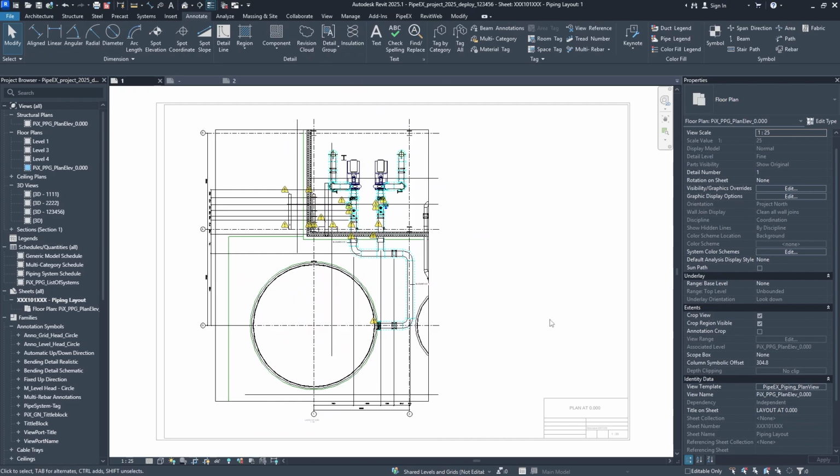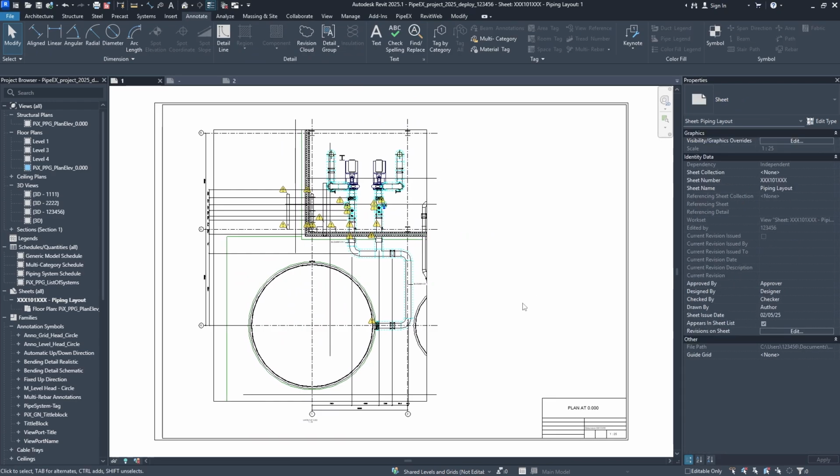You can do it the same way. In your case, you just need to create a shared parameter file, inside of the shared parameter file, if you have it already or not. Yeah, if not, you need to create it. If you have it already, you need to create a tag associated parameter, and you need to ensure that this tag parameter is added to all the categories you would like to be tagged. In my case, a generic model, mechanical equipment, pipe accessories, and I think that's it. At least in my case. In your case, of course, it can be more.